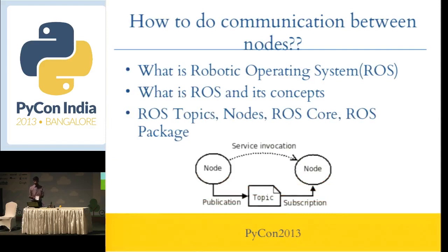And the ROS core is the master node. It's like a server. What it's doing is acting as an intermediate code between these nodes. We have two nodes, the image processing node and the Arduino node. So ROS core is standing in the center, and it connects these nodes.